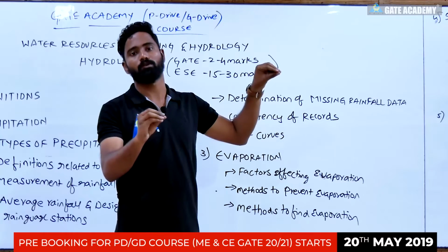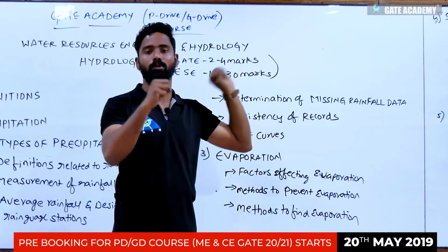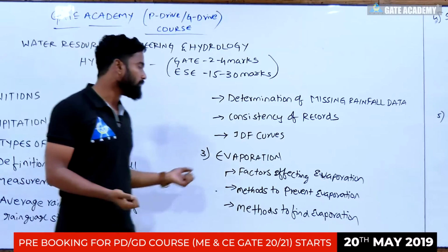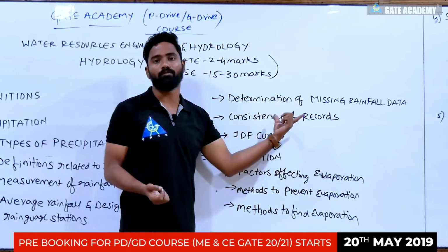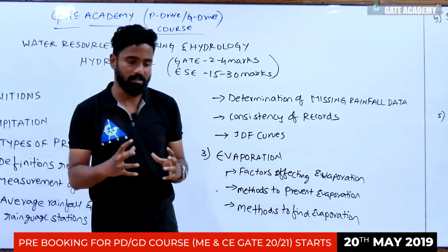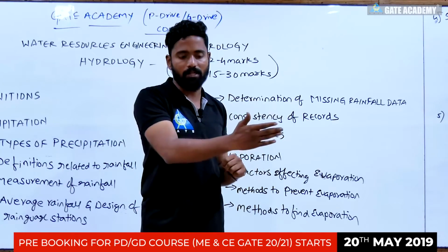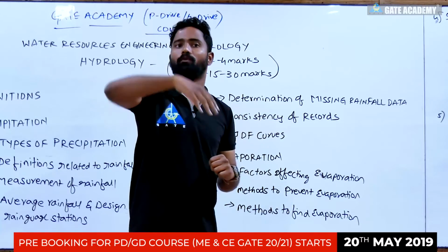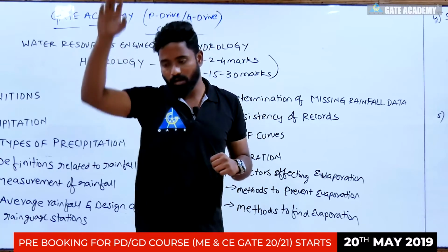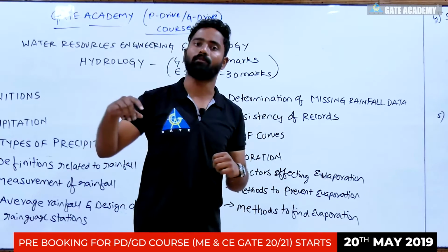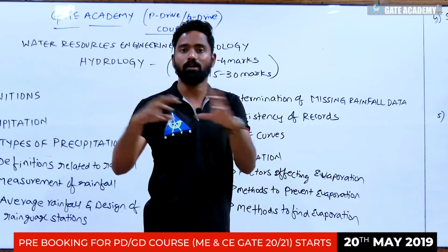you will find mass quantities only. Here it is a mass quantity, and here also it is a mass quantity, then it is called the double mass curve method. It will be plotted in reverse chronological order to find the consistency of records. Let us say one year it was 90 centimeters, another year also 90 centimeters, and suddenly it reached 180 centimeters and then reduced to 50 centimeters. So there is an uneven change in the graph and the consistency of the record is changed.